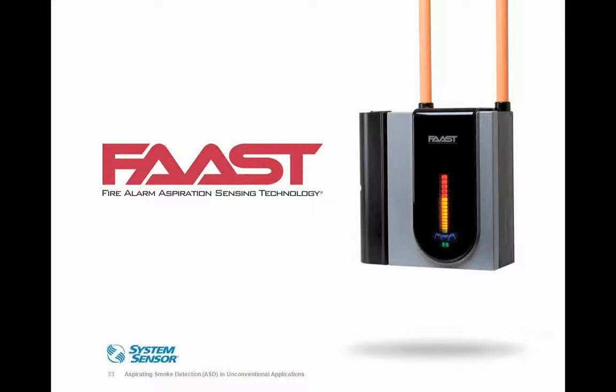In that application guide, there are a couple of approaches we take. In the application guide, that white paper they can download from our website, there's the use of heat tape on the pipe network before it enters the detector. So we can heat that air sampling, or use the outside environment. Let's say the freezer or refrigeration unit: the FAAST unit itself is going to be mounted outside of this area, of course. You can then use the ambient air temperature in which the detector is physically mounted to heat up that cold air prior to entering the detector.